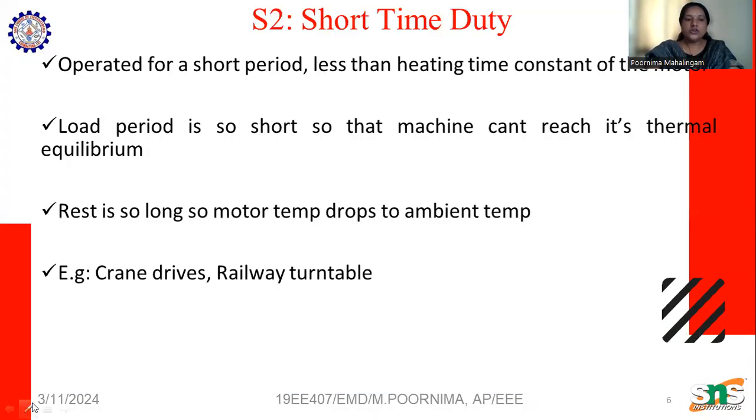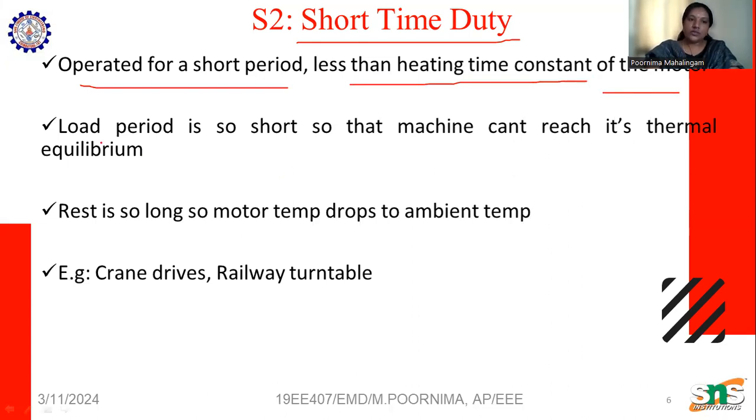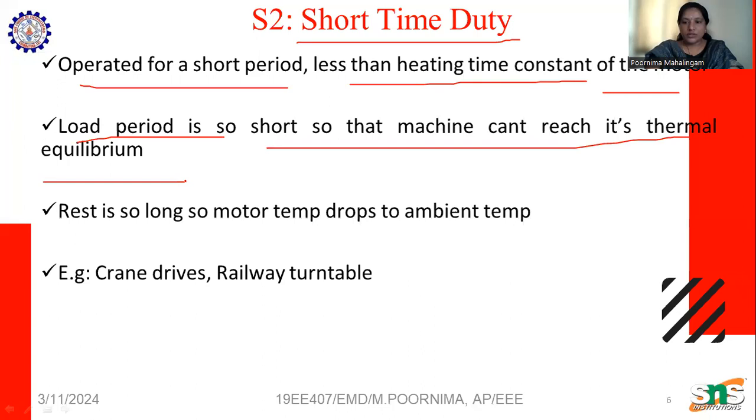The next duty is short time duty. What is short time duty? The motor operates for a short period, less than the heating time constant of the motor. Because the load period is so short, the machine cannot reach its thermal equilibrium or steady state temperature. The rest period is long, so the motor temperature drops to the ambient temperature.